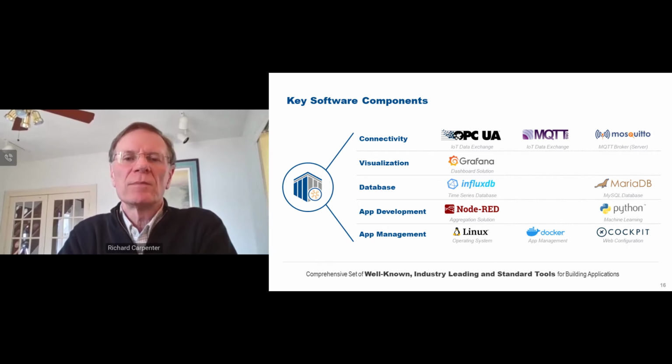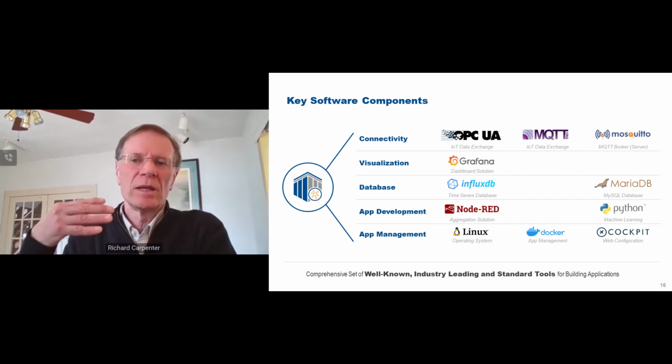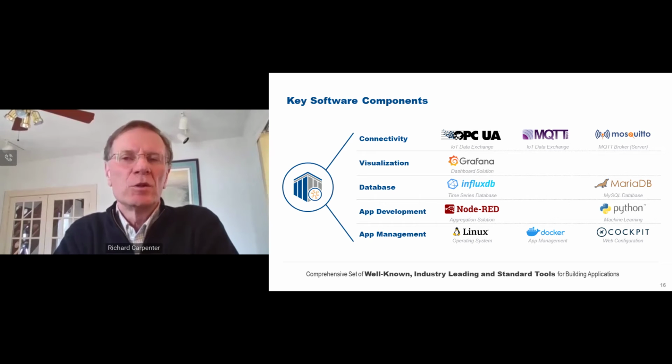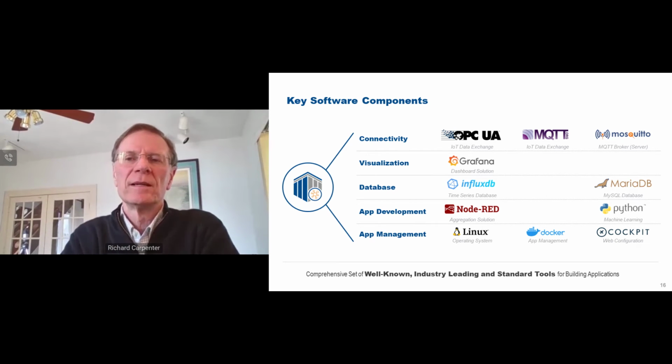We find that there are two types of logging that are required to support these little data initiatives. One's more the relational database. You want to log something once a minute, a whole series of tags together at the same time. That's useful for environmental reporting, regulatory reporting, all kinds of applications, or more traditional time series type applications where you're only logging the changes.